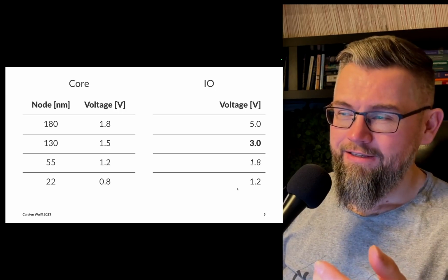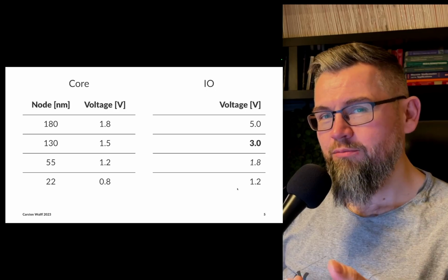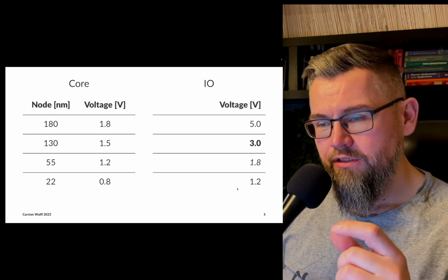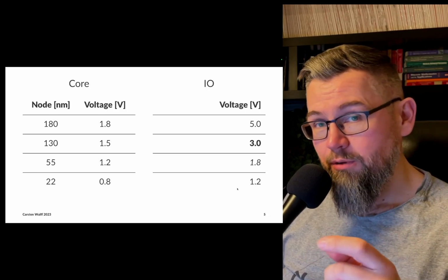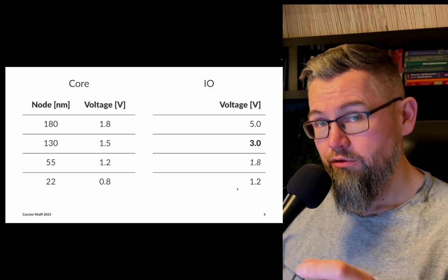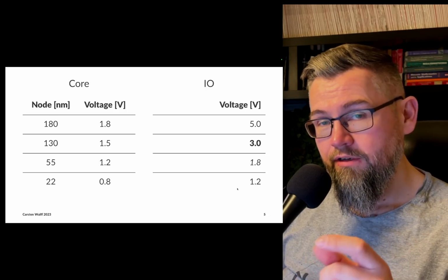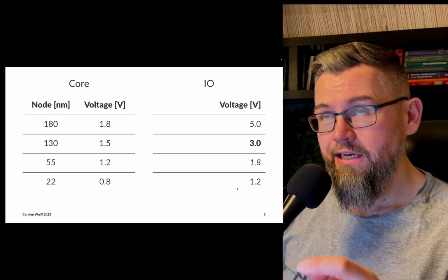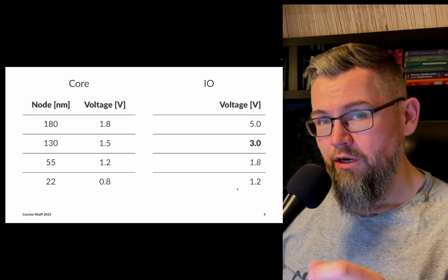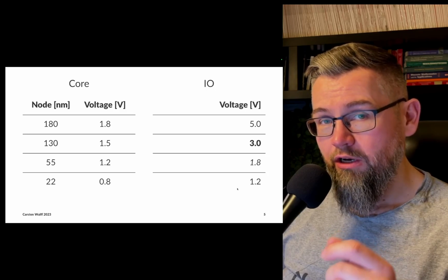But for transistors, we just have to make them survive, which means the VDD, or the supply voltage of the transistor, is just given for a certain technology. You pick a technology and you have a set voltage. You cannot really exceed that by much without really knowing what you're doing and paying careful attention to reliability.